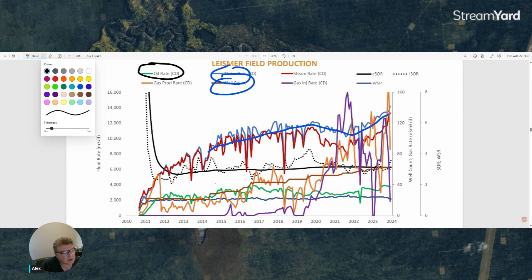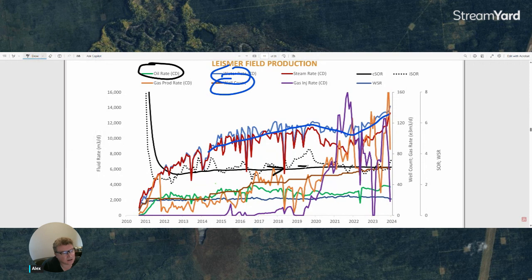So you can see here the CSOR was increasing, but now it's kind of declining. And NCG co-injection helps with that CSOR declining. Now, you could say, well, maybe it doesn't decline that much, but it does relative to oil uplift, which is here, because before you produced less oil and now you're producing much more oil.